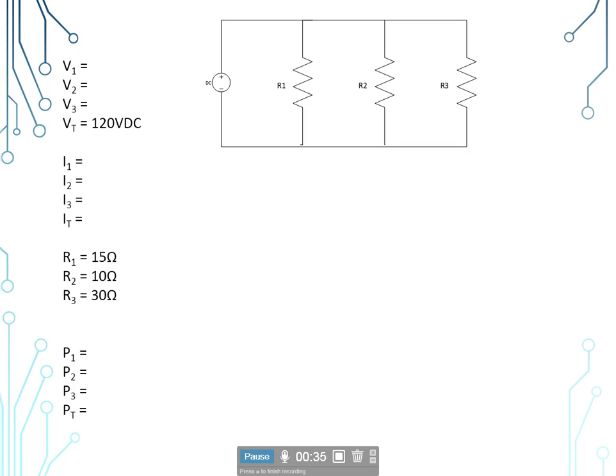We need to first trace our circuit, make sure we have more than one path for the current to flow. So here we go, we come to a node, we've got a path here and a path here, another node, a path here and a path here, to this branch, all the way back to the node where they connect back together, there and there, and back full circle to our power source. So we do have 2 or more paths for the current to flow, so this is a parallel circuit.